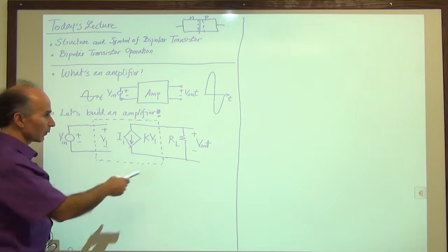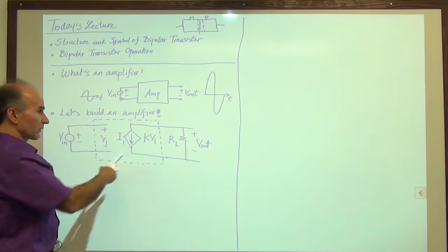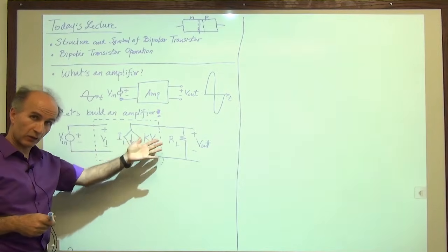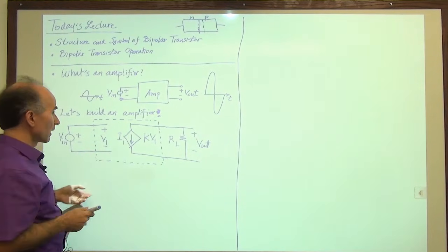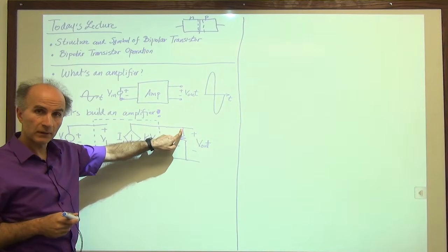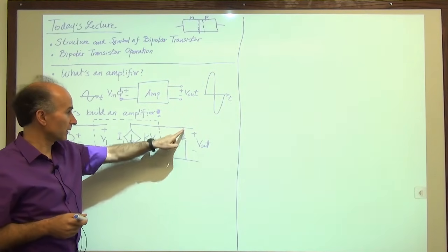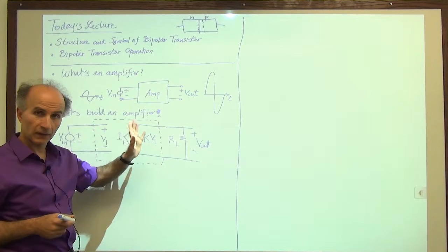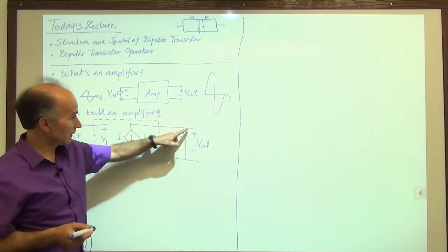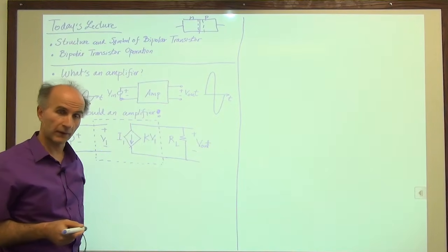Okay, well, how do I analyze the circuit anyway? This is very simple from circuit theory point of view. You have analyzed much more complex circuits. What I will do is write a KCL at this node. I have two currents, this current, and nothing else. So this current plus this current has to be 0. This is not going anywhere, so there's no current there.